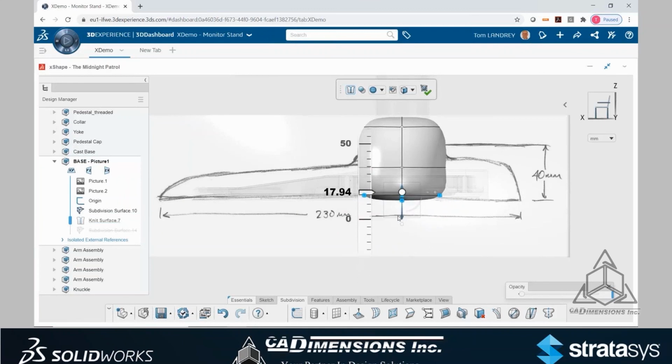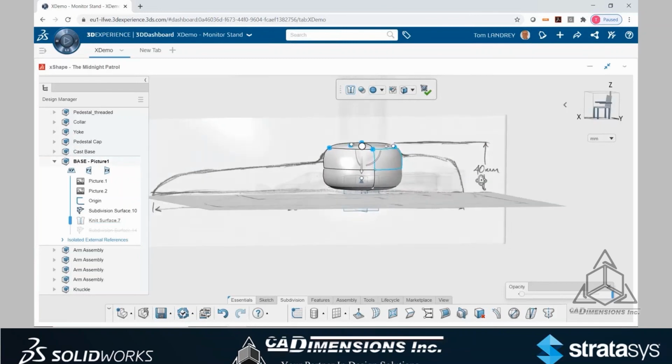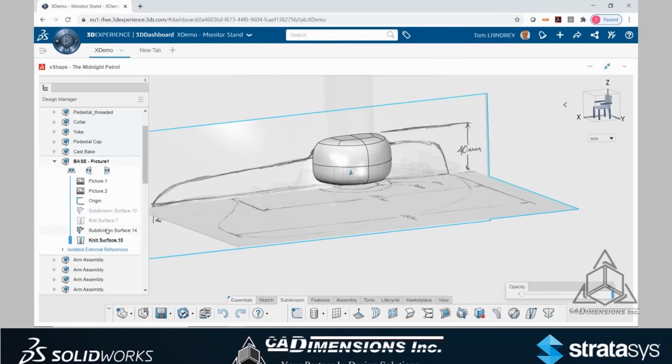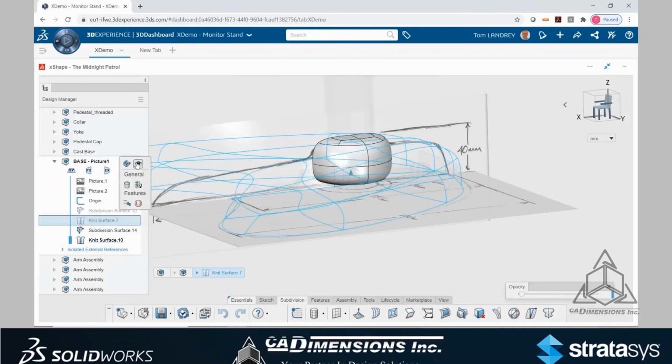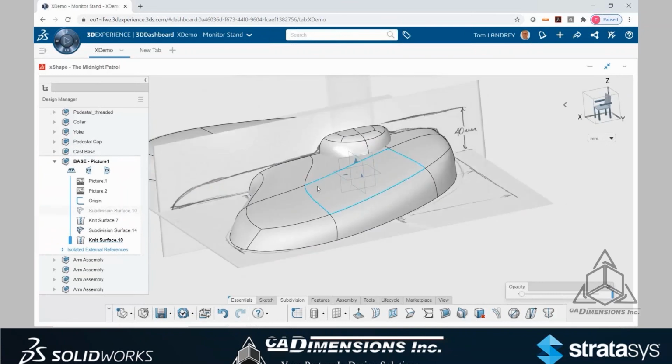Now here, I probably should put a seam on the bottom, but I'm just going to move this up. So I want that cylinder to be completely inside the other part because we're going to do a Boolean operation on this later. And I'll just move this guy down, just trying to match up the edges, and pretty close. Again, quick eyeball. Okay, so I'm pretty much done in xShape. We turn that back on so you see other parts, we hide it. And I got 2 primitives working in xShape.